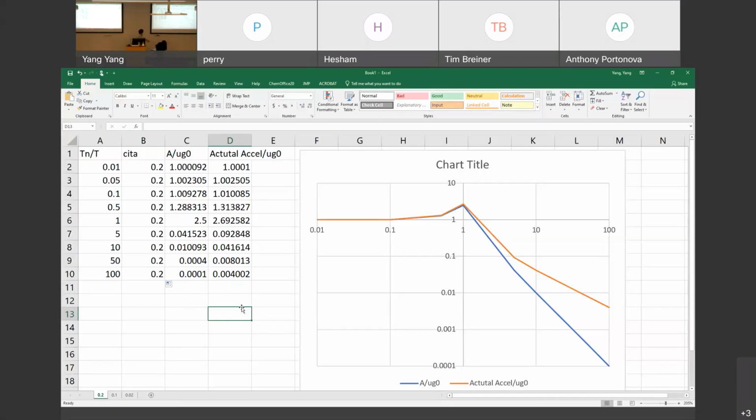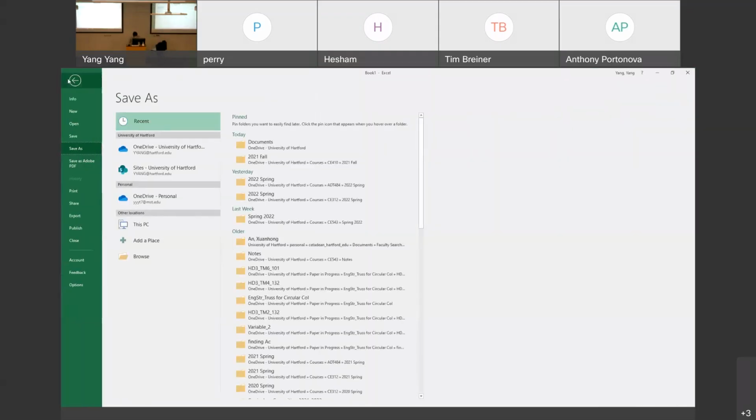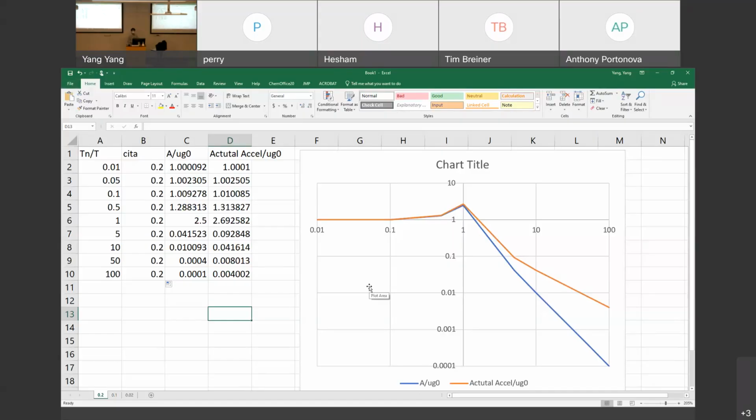So this is the response spectrum. This is the pseudo as well as the actual acceleration response spectrum under a harmonic ground acceleration. So the pseudo one is not always equal to the actual one. This example is very important because it tells us why we call the pseudo one the pseudo: because it's not the actual term.